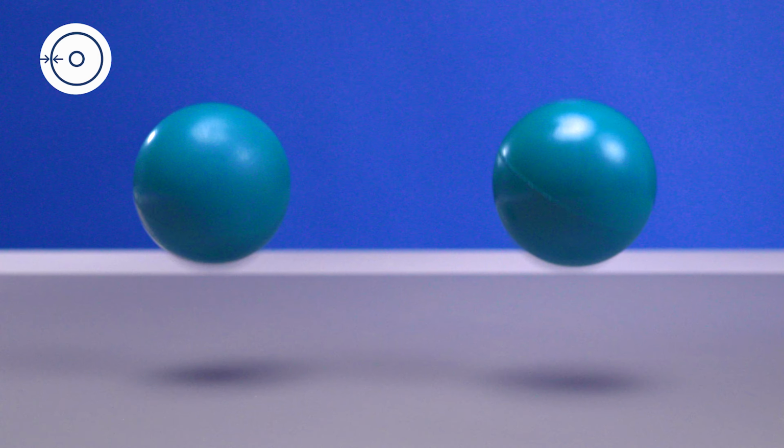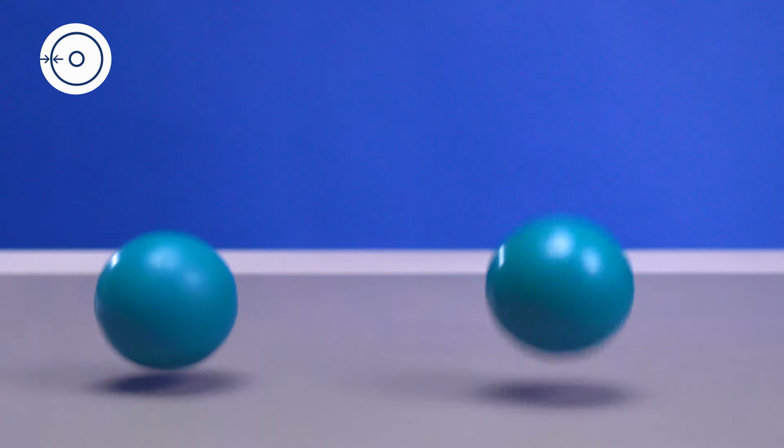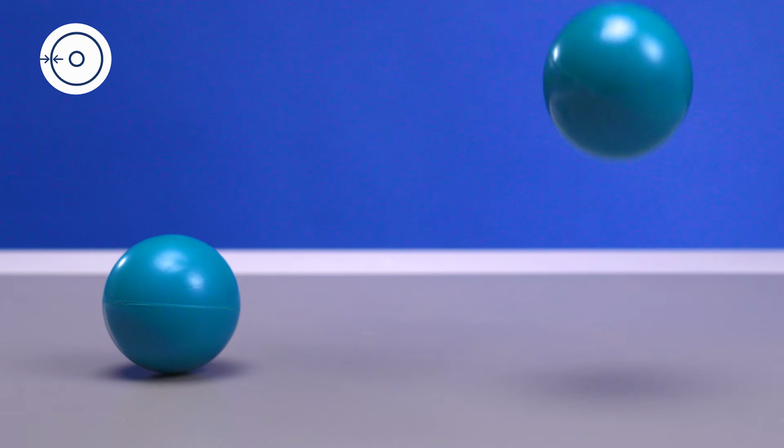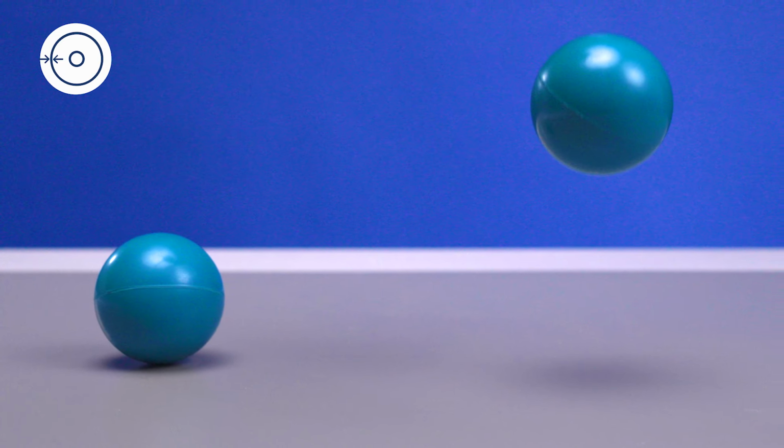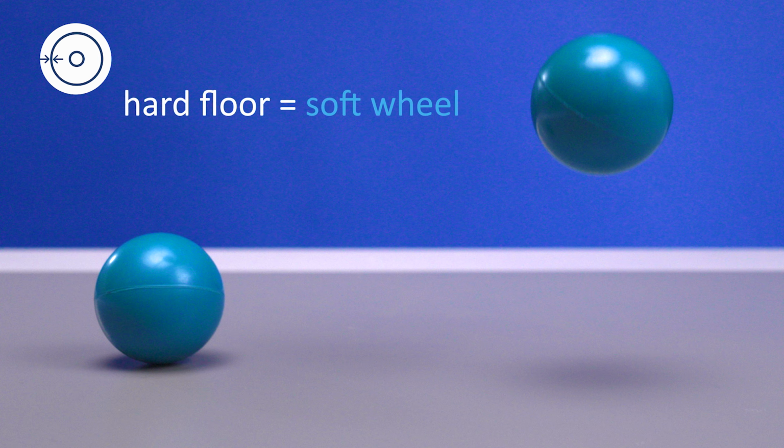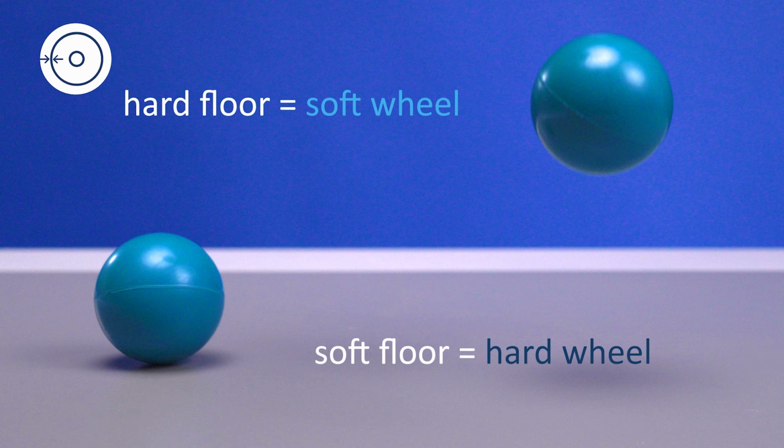These two balls illustrate the differences between hard and soft materials. One is softer than the other one. Now, let's compare them. As you can see, the soft material absorbs shocks very well. This simple rule of thumb can be used to match the floor and the wheel. For a hard floor, use soft wheels, and for a soft floor, use hard wheels.